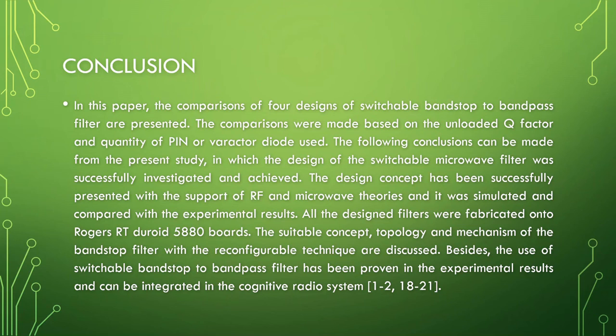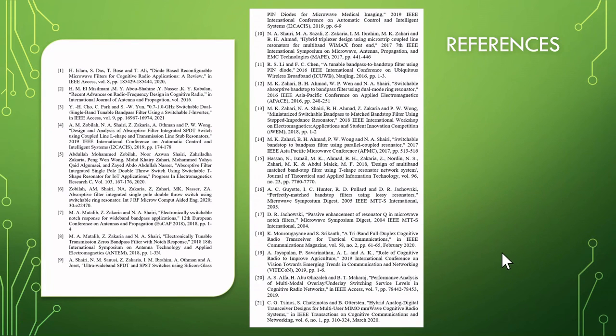All the design filters were fabricated onto Rogers Duroid 5880 boards. The suitable concept, topology, and mechanism of the bandstop filter with the reconfigurable techniques are discussed. Besides, the use of switchable bandstop to bandpass filter has been proven in the experimental result and can be integrated in cognitive radio. So these are the references for my paper.